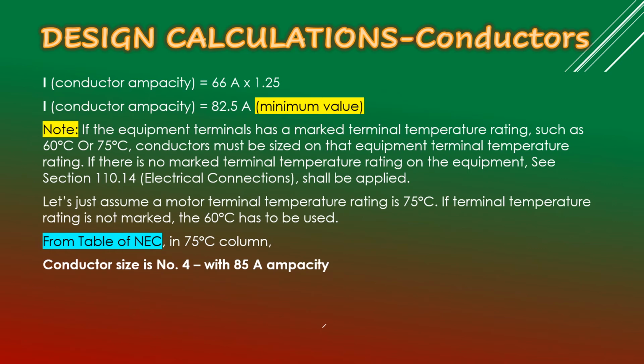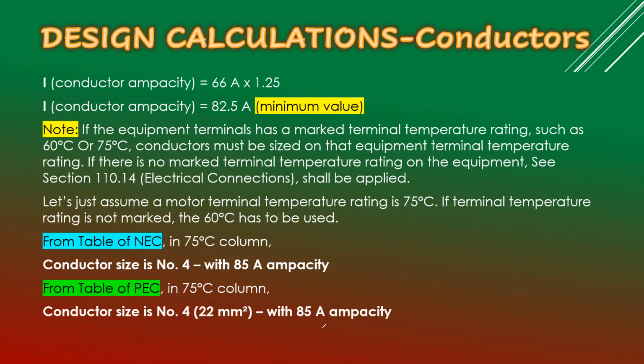Conductor size is number 4 with 85 ampere ampacity. Also, comparing from the table of Philippine Electrical Code PEC, in the 75 degree column, conductor size is number 4, also equivalent to 22 square mm with the same 85 ampere ampacity. So coincidence that they have the same ampacity.